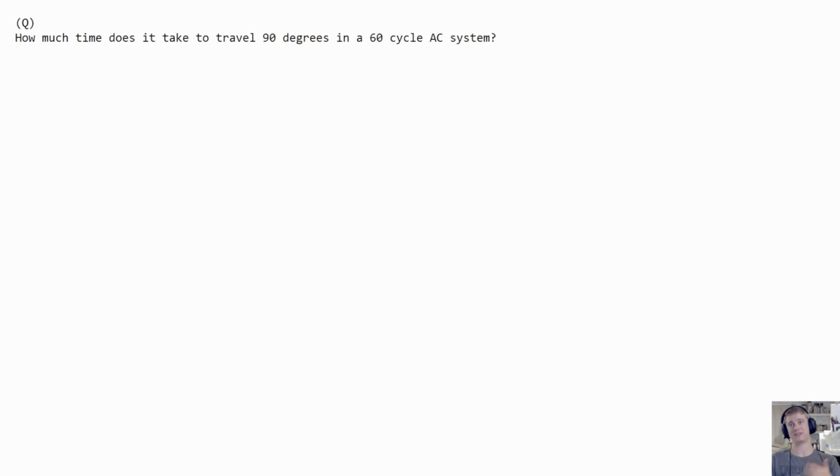Next, how much time does it take to travel 90 degrees in a 60 cycle AC system? Now, if you understand sine waves, or if you saw my sine waves questions and answers video, then this will be no problem. Okay, so to first think about it, we have a 60 cycle AC system. So we know that in 1 second, we have 60 cycles. We could also say that if we have 1 cycle, then we'd have 1/60th of a second. Since 1 cycle is 360 degrees, that is the same as saying 360 degrees, 1 cycle, is 1/60th of a second. Now if we think 90 degrees of 360 degrees, instead of 1/60th of a second, we have 1/240th of a second.